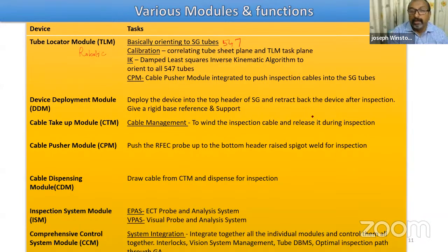Then the complexity here is the development of inverse kinematic algorithm, where it is a completely numerical technique. And apart from the development of the numerical algorithm, the biggest challenge is stability of such algorithms. Numerical instabilities can come whenever there is a division by 0. Particularly, these are matrix-based algorithms. When the determinant becomes 0, the invertibility becomes a question mark. So we have to use some techniques like damped least squares technique to avoid numerical singularities.